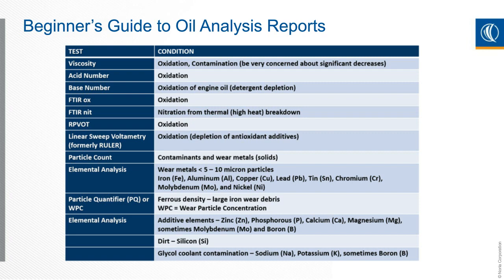And most of the tests we're looking at and talking about so far are going to require some kind of reference, some kind of baseline. So it's important to know what that baseline reference is, such as your new oil or a previous sample, so you know exactly what you should be expecting.